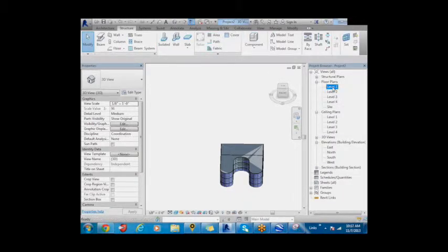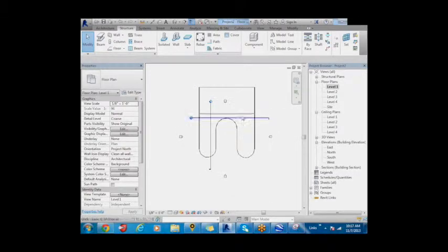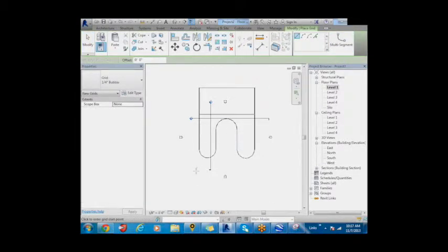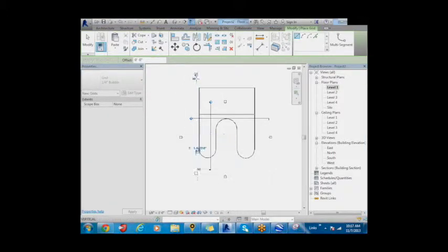If you remember, that's within the structural tab. The cool thing about grids is that regardless of whether you put them in level 1, 2, 3, 4, or 5, they always show up on all the other levels, because you need them to snap your building objects to. So let's do that. Putting in our grids, you basically want to go from bottom up.